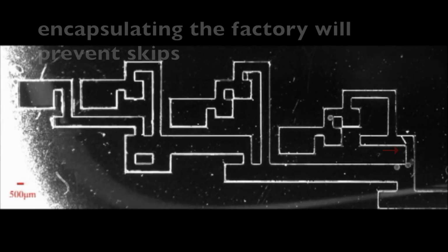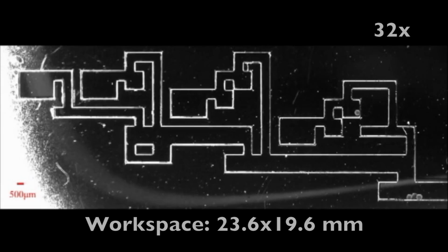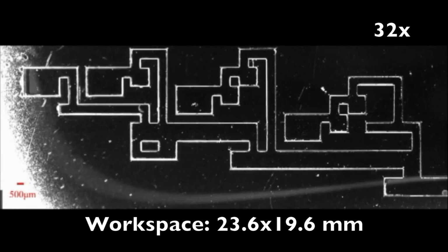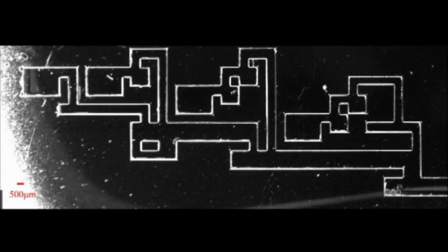Friction from the walls is the largest challenge when maneuvering through the factory. To overcome this friction, the control input is pulsed. The pulsed control input does cause some of the microbots to temporarily move backwards, but they reach their destination by the end of each control sequence.